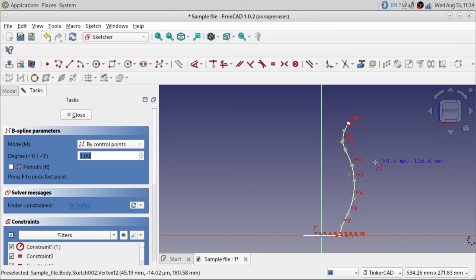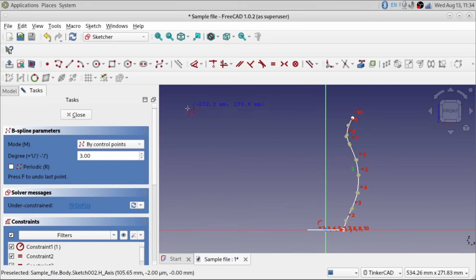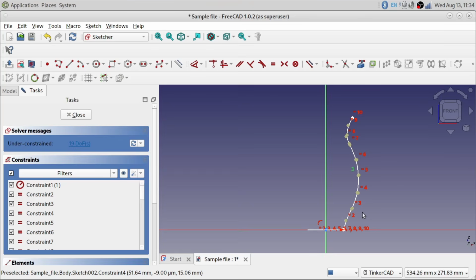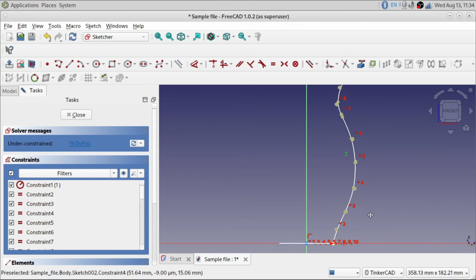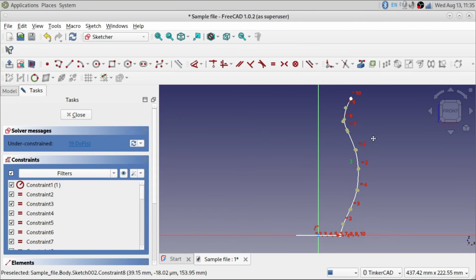something like that. Let's say that's the shape that I want for my vase. And what I want the AI to do then is I want it to scale the sketches so that their edge lines up with the B-spline. That way I can simply just draw a profile, and hopefully the macro will just automatically create however many sketches it needs to create for the height of the vase. And the height of the B-spline, let's see what the height is. Right now it's 180 millimeters.